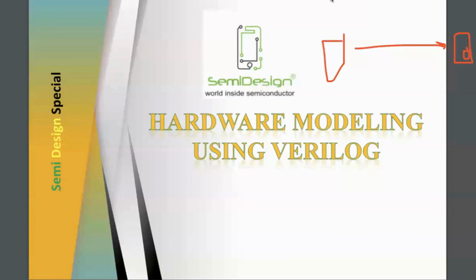Data will be stored. The data address size will be maybe 32-bit, and the data size will be 32-bit or 8-bit. Every bit we are transmitting serially. Suppose in a UART, I2C, or APB protocol, if you consider 8 bits, 0 to 7, they will be transmitted sequentially, one by one.